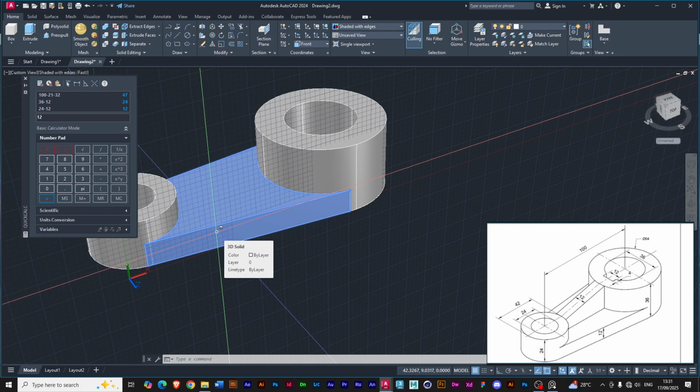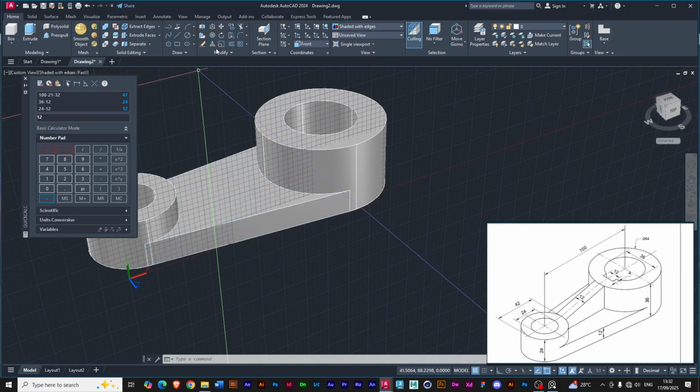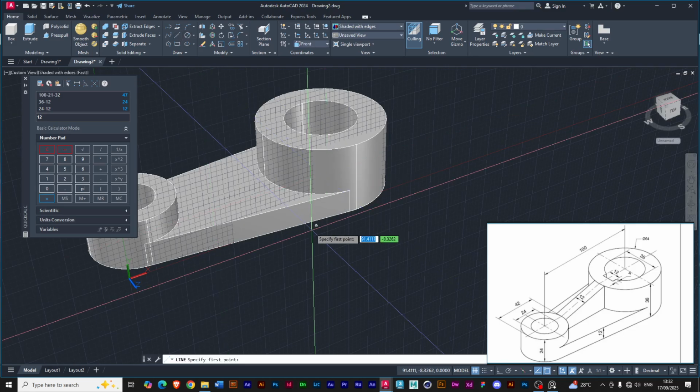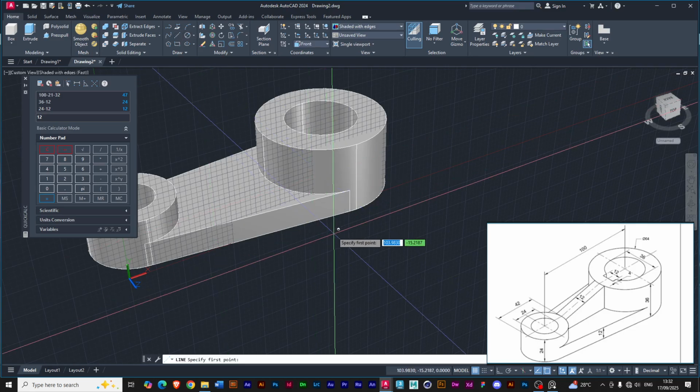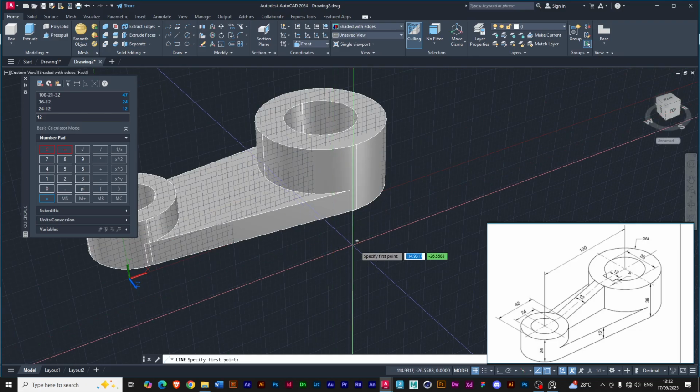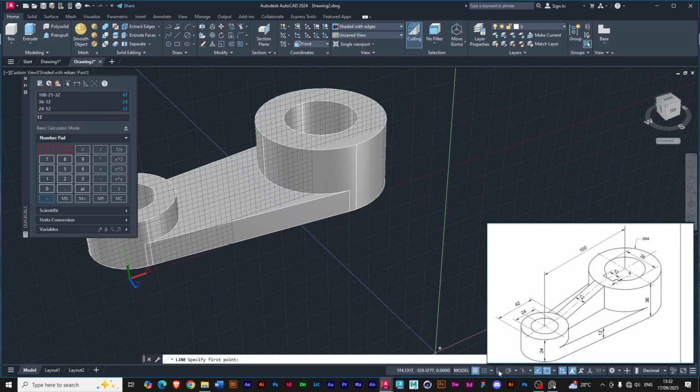Take the line tool and do those drawings, because now that you've switched to the front plane, it's going to draw on the y-x axis on this grid. So with the line tool, you pick a point. You can use auto mode so that it's straight lines.